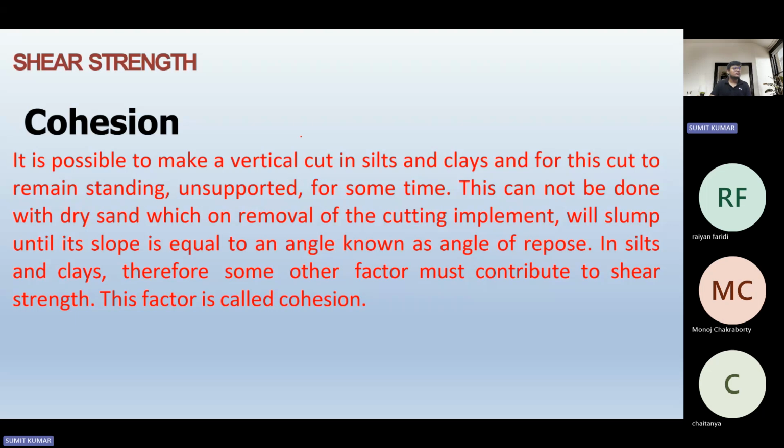As you know, cohesive soil doesn't collapse very easily. But if it is sandy soil and you want to make some excavation, some support needs to be provided, which isn't required for cohesive soil up to a certain depth.